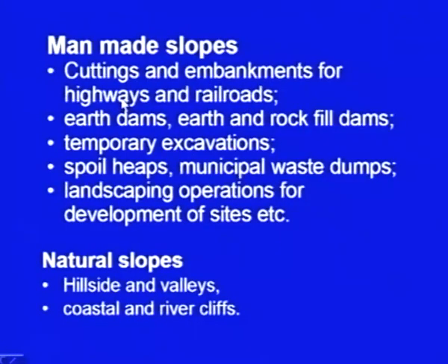they pass through an area which is near a river, you might have seen that the highway is kept at a little bit higher level. The idea is we try to keep it above the high flood level, so that even during floods these highways are not blocked. To do that, we have to make some sort of embankment, and on that embankment the highway is placed.